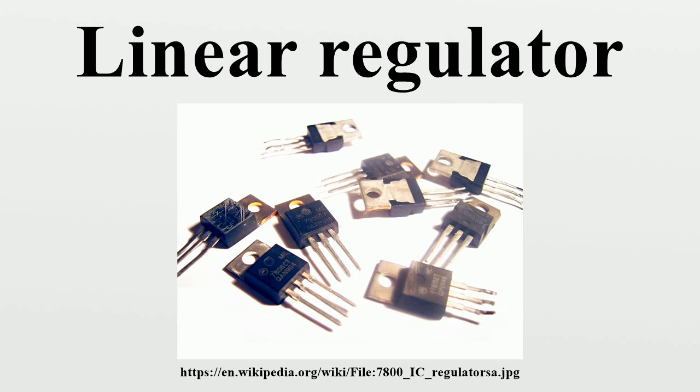Variable regulators. An adjustable regulator generates a fixed low nominal voltage between its output and its adjust terminal. This family of devices includes low-power devices like LM723 and medium-power devices like LM317 and L200. Some of the variable regulators are available in packages with more than 3 pins, including dual inline packages. They offer the capability to adjust the output voltage by using external resistors of specific values.